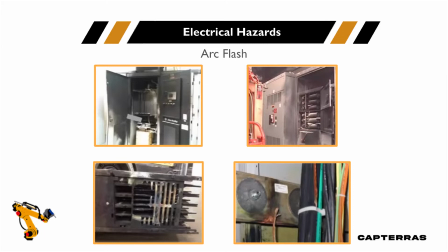But prior to this, he had been off work for a while, because prior to this he was not in arc flash gear, and he was doing some work on equipment and was involved with an arc flash. And unfortunately, that arc flash caused his clothing to burn and melt to his skin. He was not wearing arc rated clothing. He was wearing synthetic fiber clothing, and of course he had to go through a lot of skin grafts and a very painful time of recovery and healing. So we'll talk about the fact that we do not wear any type of synthetic fiber clothing unless it's non-meltable and meets the standards.